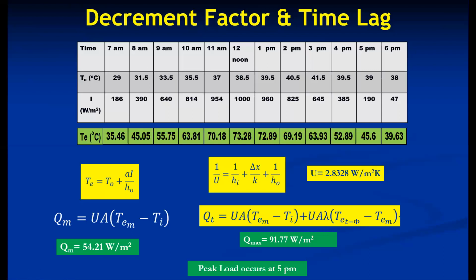So these are the standard problems. In some cases, maybe brick conductivity is given, maybe some plaster is used. In that case, you have to add these conductive resistances while calculating U. So these are the variations only, nothing else.